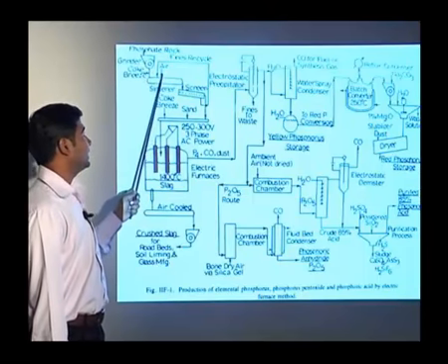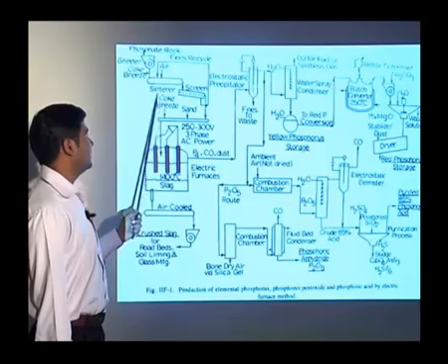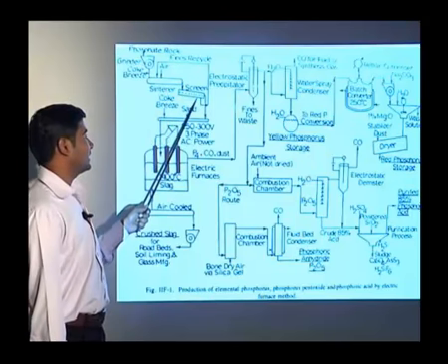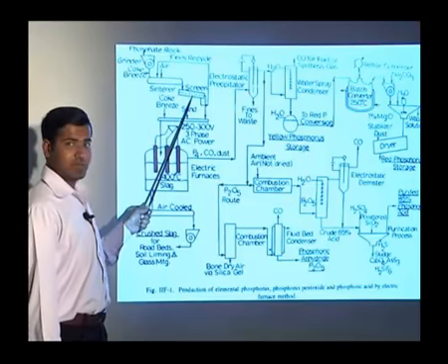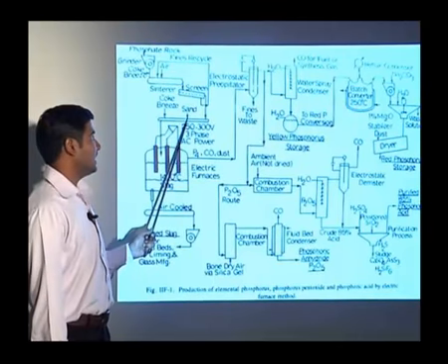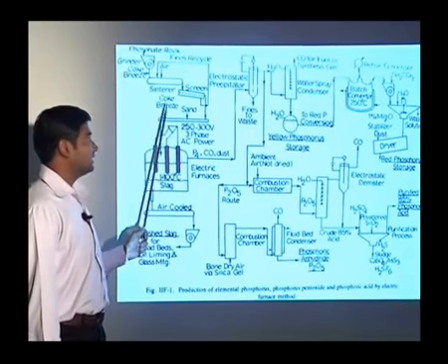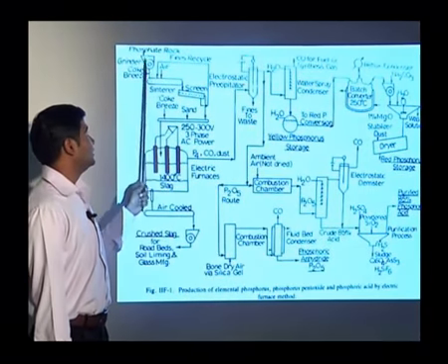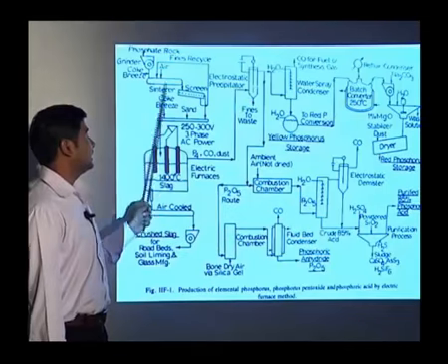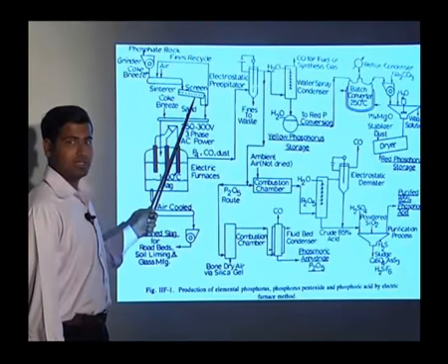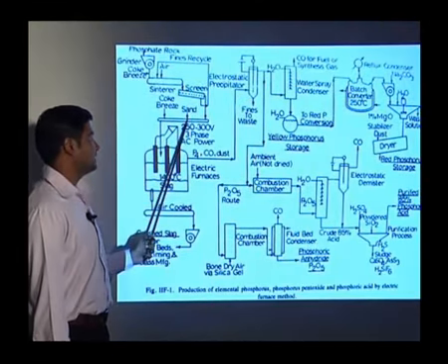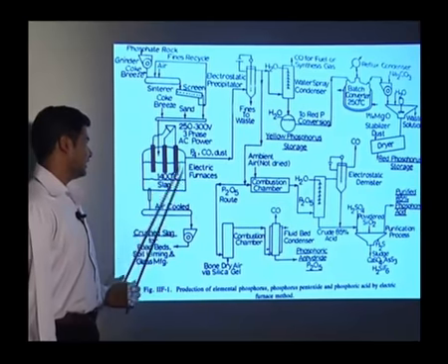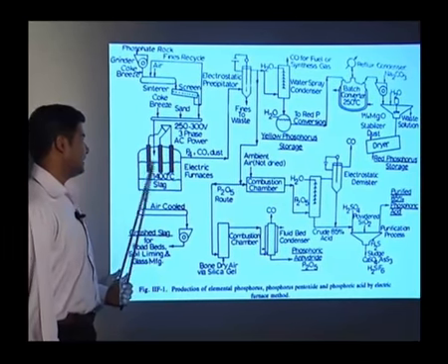Then, with air, we screen them to get the desired particle size. Then we add sand and the coke breeze. Here, coke breeze means very fine particles of the coke. So initially the phosphate is ground and then screened to get the desired particle size, then the sand and the breeze are added. Then the electric furnace is used.